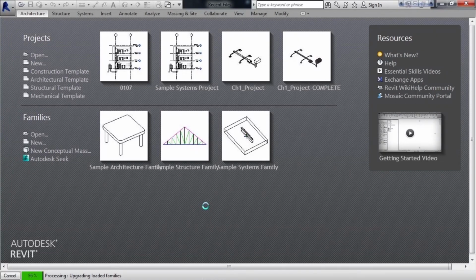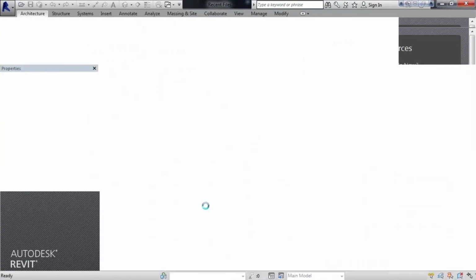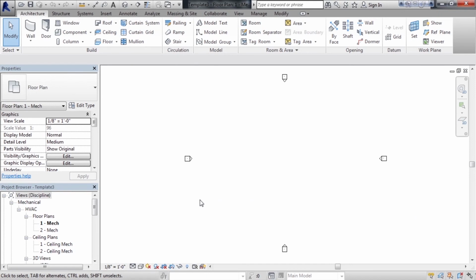And then it's going to open up and I'll see that template with all of its functions and all of its settings, and I can go in and start to make any modification I want. Now, once I save that template, it will be saved back to the 2015 version. There is no saving back to previous versions in any flavor of Revit. So once you open and save something in that version of Revit, you have to work in that version or a newer version. So here's that template.